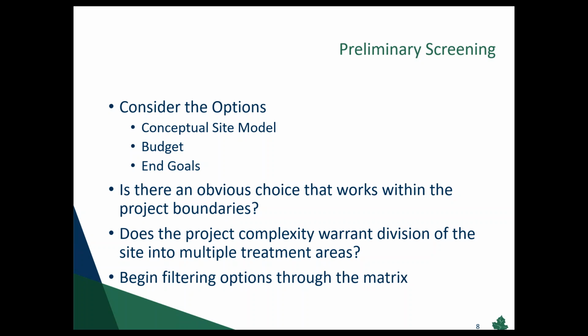So the approach we took there, we started off with a dual phase extraction. And this was a mobile application, so we did a couple of 7 consecutive day events running 24 hours a day, and we were able to get the mobile LNAPL down to pretty much a sheen, if not gone completely, in a few limited areas of the site.